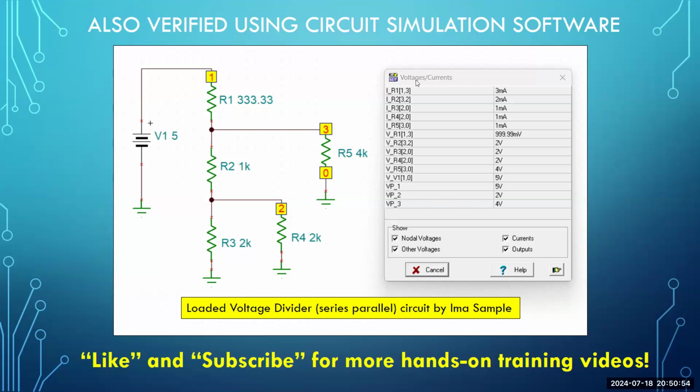Now let's do one more thing and see if the voltages across each of the voltage divider resistors match. 1 volt here, 2 volt here, and 2 volt here. Take a look at VR1, it's supposed to be 1 volt. Wow, the simulator does also simulate tolerances. In other words, it does also simulate some margin of error given the resistors being 1% or 5%. And so the simulator simulating the margin of error instead of 1 volt gave us 999.99 millivolts. That, my friends, is 1 volt.